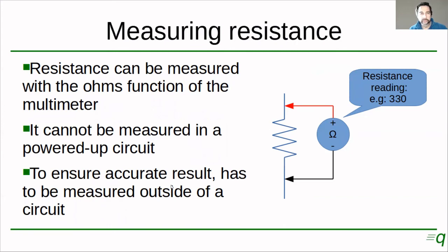But you have to be careful with a couple of things. First, it cannot be measured when the circuit is powered up. If the circuit is powered up, that will mess up your measurements.